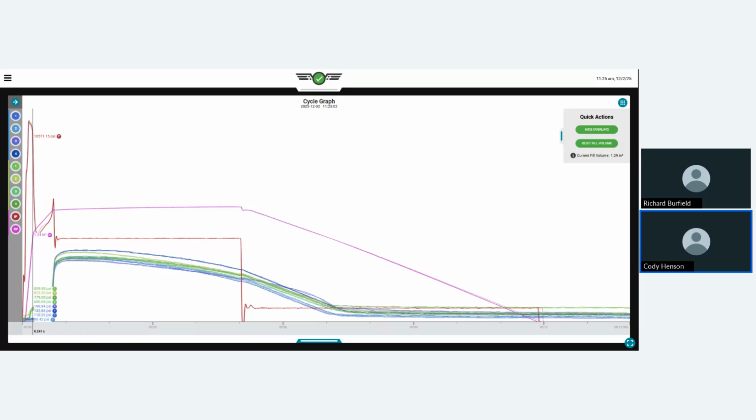And it can also help you understand whether your process can absorb those shifts in viscosity successfully. And when I say successfully, I mean, can the process produce the same cavity pressures that provide a good part, even as the material viscosity starts to shift?